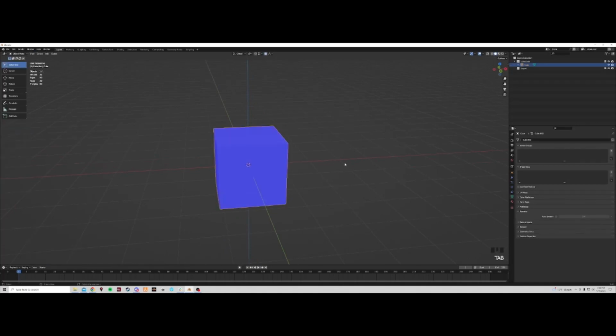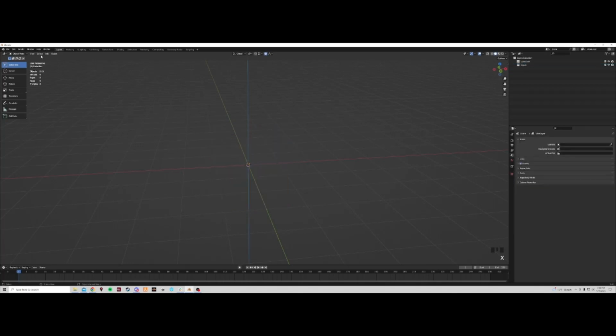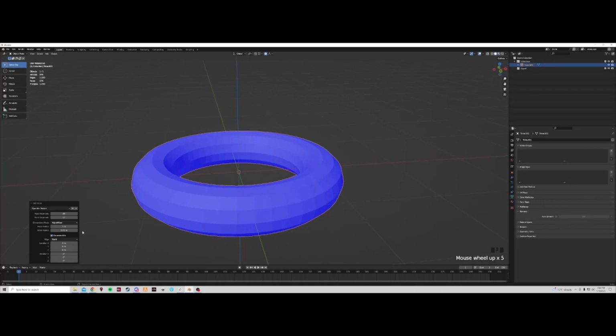For example, here, I'll show you another option for when those things pop up. If I add in, say, a torus, okay? Oh, here. Let me delete everything so I just have the torus. If I bring the torus in here, I now have settings for the torus. It'll pop up like this. You can change the amount of segments that are around it. Make it way more high poly or lower poly. You can change the segments around the loop of it.